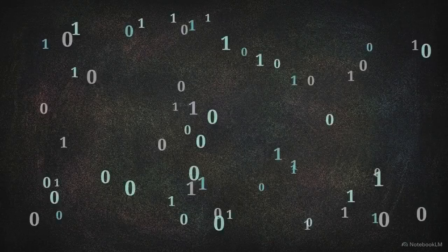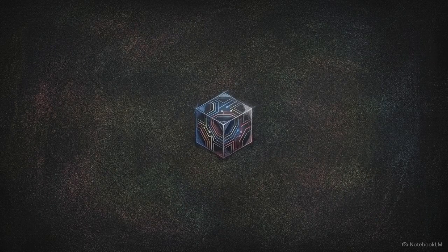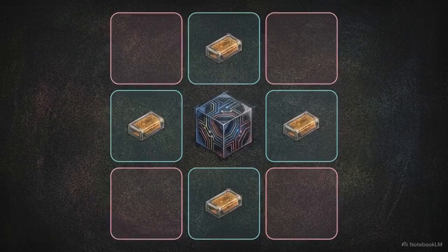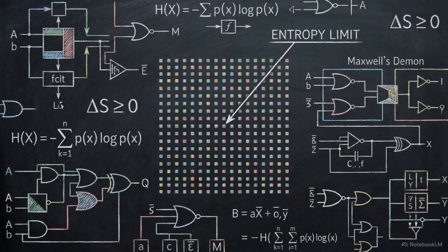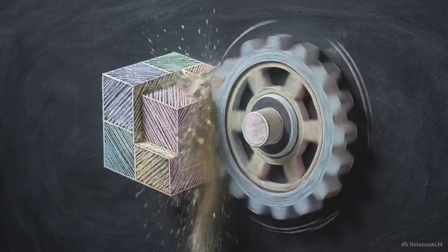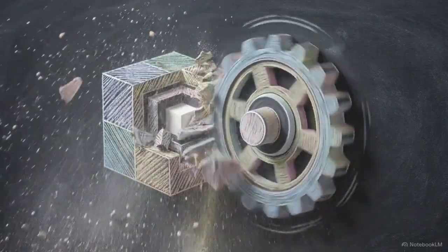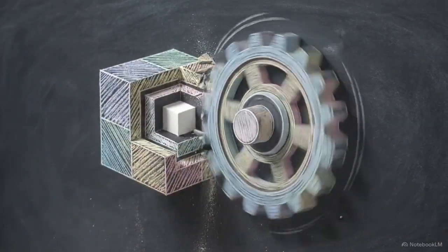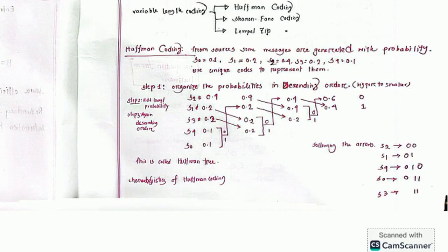Once the signal is digitized, the system executes an apparent paradox. It spends immense computational effort compressing the data, only to intentionally inflate it moments later. The compression phase is source coding. Driven by Shannon's concept of information entropy, the objective is to strip away every trace of statistical redundancy from the file. This probability tree illustrates one of the most efficient algorithms for this task, Huffman coding.